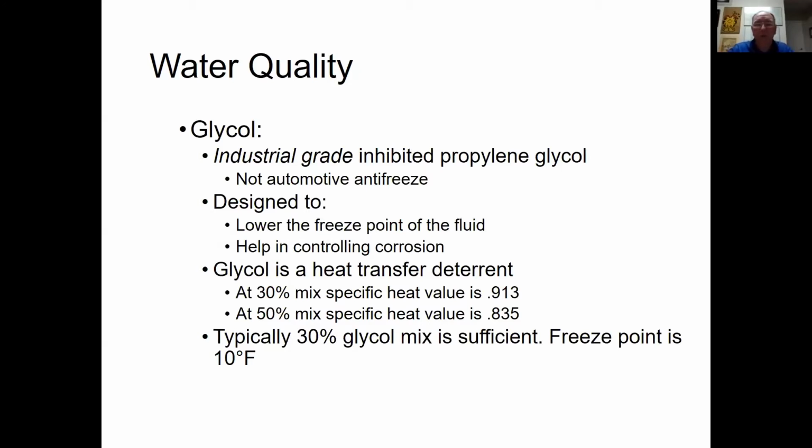Other ways of doing water quality, I guess is the best way to say it. You can run glycol. Typically, glycol is not necessary unless you're running less than 48 degrees Fahrenheit in a chiller. And as a side note, please don't put glycol in a tower system. That's not what it's designed for.